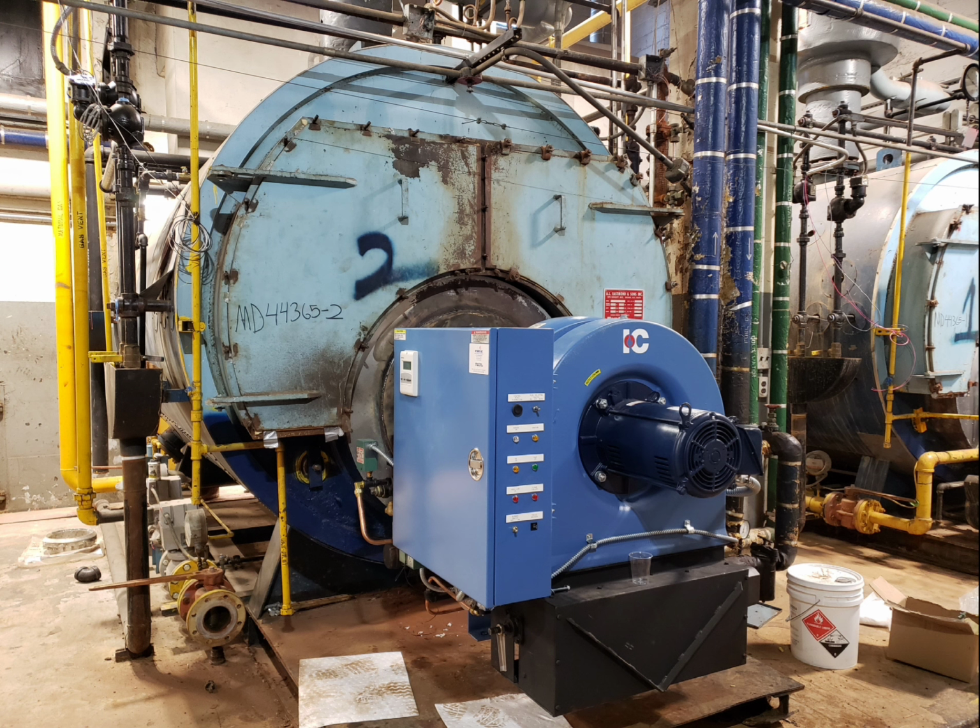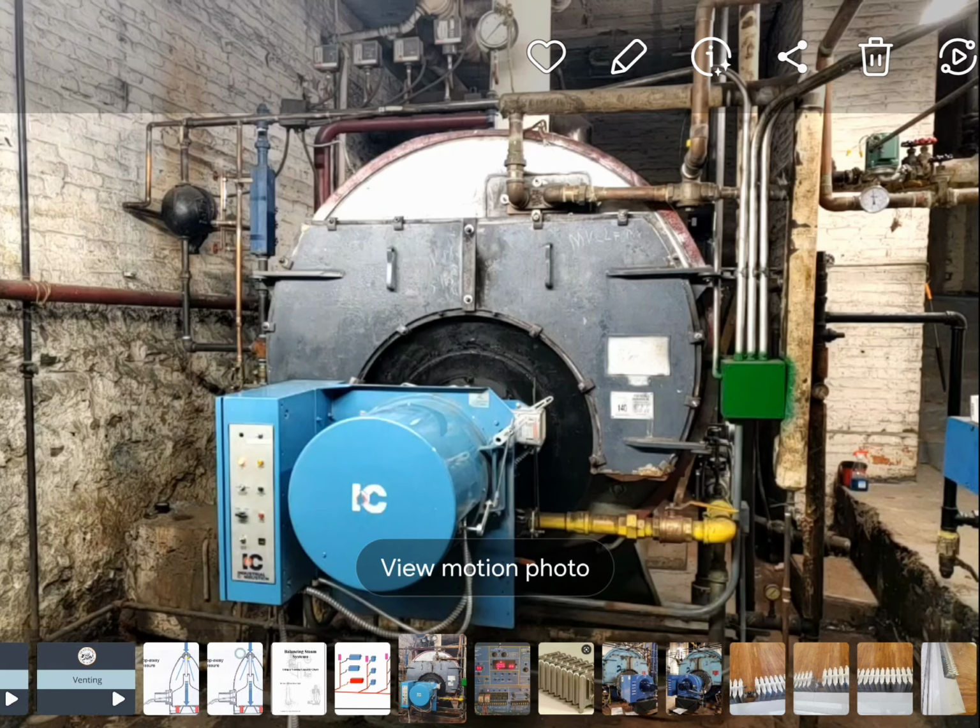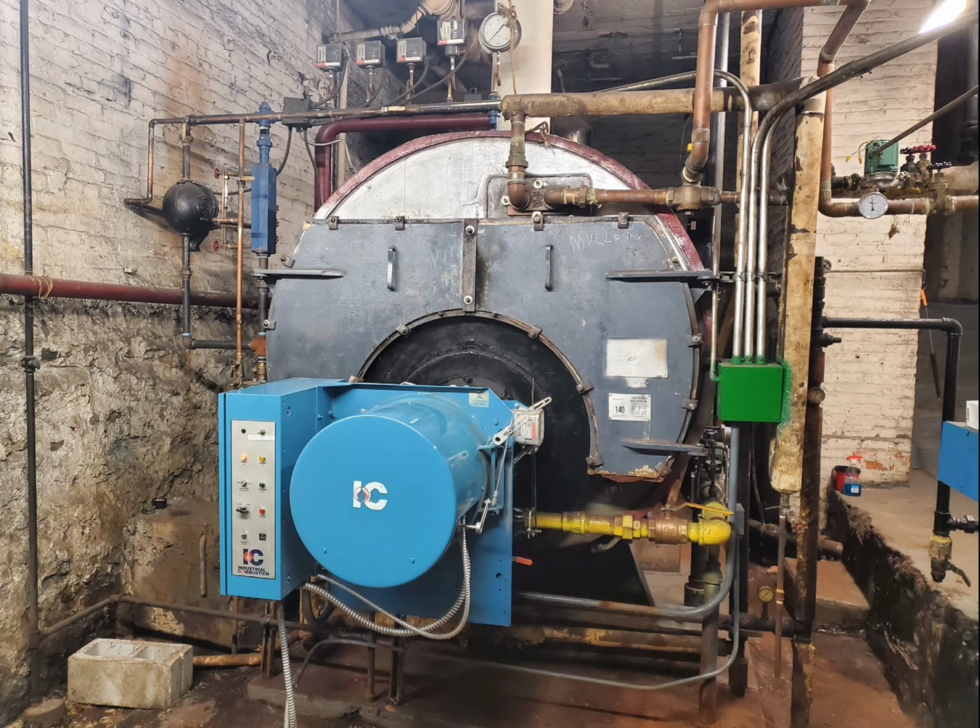As a matter of fact, with this boiler here, it's either this one or one of the boilers I had in these buildings. Like I told you, it typically would be about a minute of a pre-purge of it just blowing air inside of the combustion chamber. And the reason why it does that is to push out gases that might be lingering in there, so you don't have a blowback.